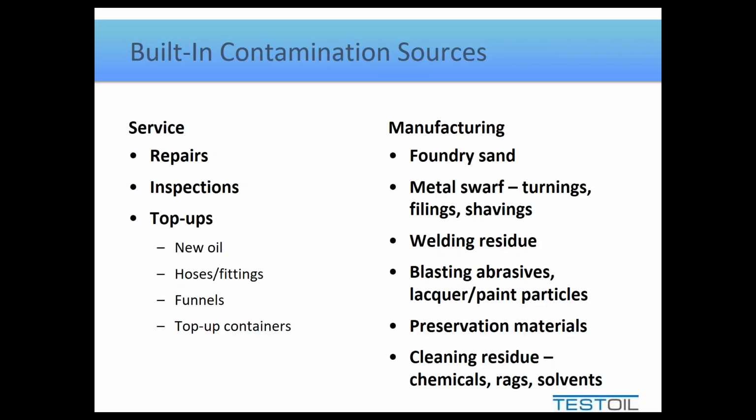When we weld anything, oftentimes we're welding from the outside only. We're not doing anything on the inside, so we're not noticing any of the little spatters that are created. And this can also generate particulate; many of these spatters can be quite small and even damaging. When we go through rebuilds or do some of the commissioning, we may use sandblasting or bead blasting. When we do this, the beads that we're using or the sand that we're using is not necessarily that damaging because it tends to be quite large, but as it removes material, whether it be oxides, lacquers, paints, whatever it's doing, if we don't fully flush all those out, the remaining particles can be quite damaging.